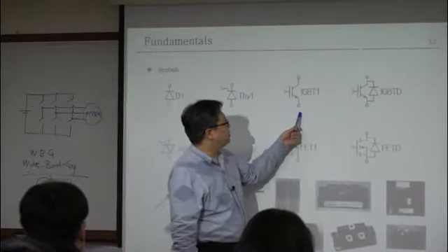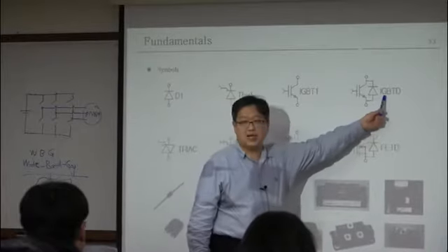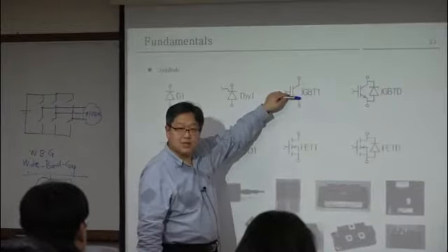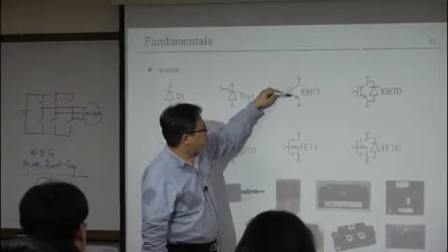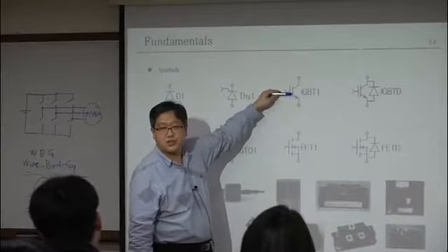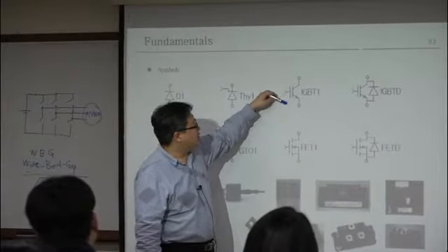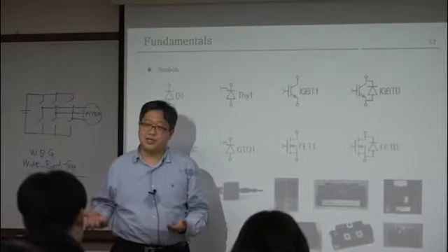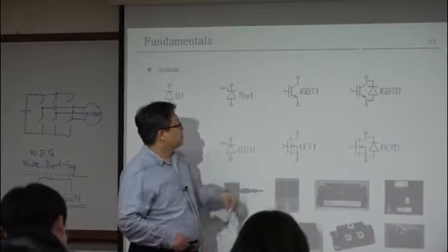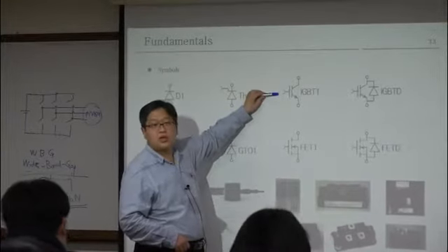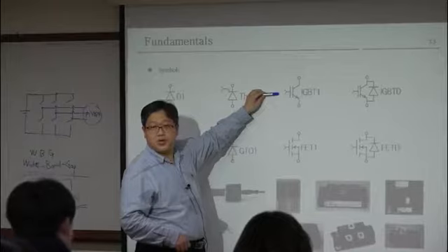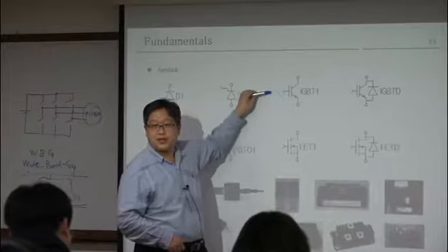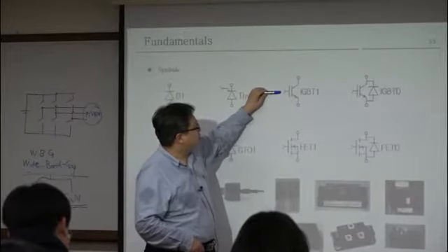And this is the IGBT. And this IGBT with the diode. Then it looks like BJT. Also, you have this symbol that can be considered as a capacitor. So it is a kind of mixture of MOSFET and BJT. So, do you give the voltage or current here? Voltage, why? Because its driving gate part is similar to the MOSFET. So, you apply a voltage.